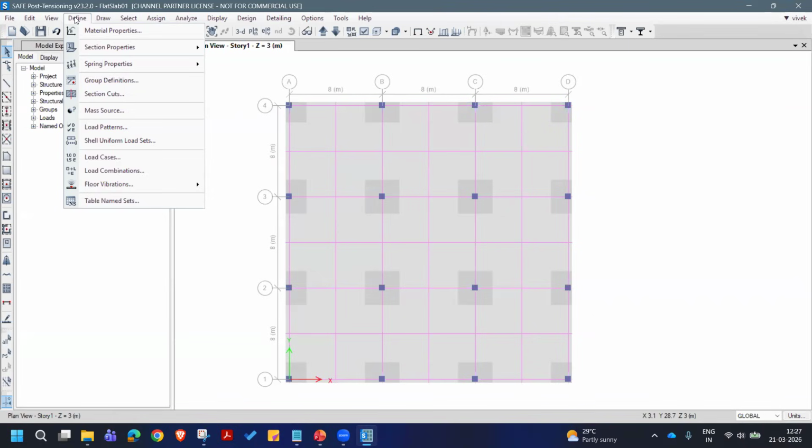So the important thing to note here is you should not apply any modifiers to the slabs unless special conditions require modifying the slab stiffness. So full stiffness is used, unlike in ETABS where you reduce the floor slab stiffness for the superstructure analysis. Here in the slab design and the long-term deflection checks, you'll use the full stiffness. That is, no modifiers. Right.